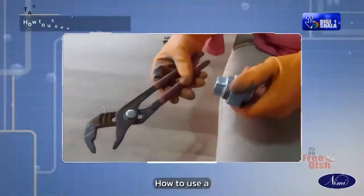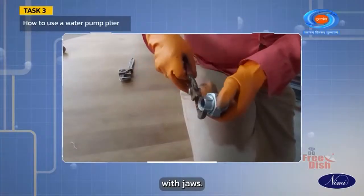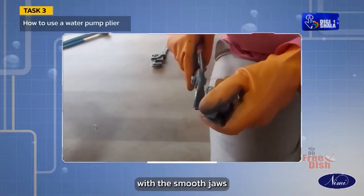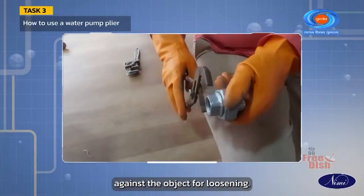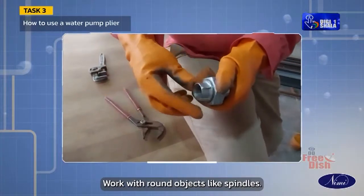How to use a water pump plier. Hold the workpiece with jaws. Use a firm grip on the water pump pliers with the smooth jaws against the object for tightening and the teeth against the object for loosening. Work with round objects like spindles.